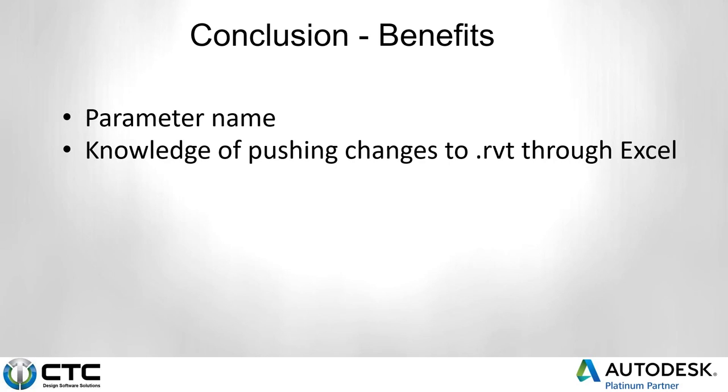So you're matching parameter names from Spreadsheet Link to Family Processor. It's all connected to one another. So creating new shared parameters and going quote unquote rogue with them, you've got to be really, really careful with consistency so that if you have to make changes to the project or the family editing environment, you at least can play the parameter matching name game.